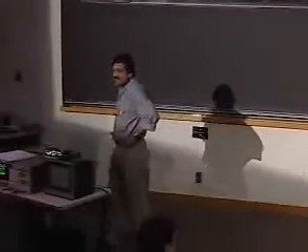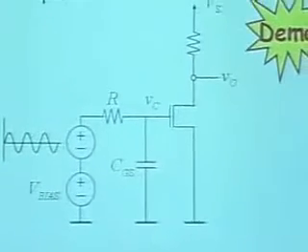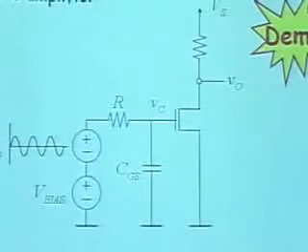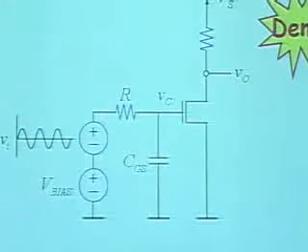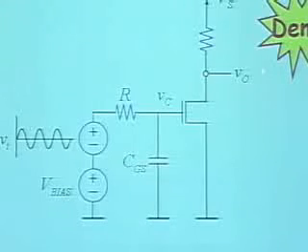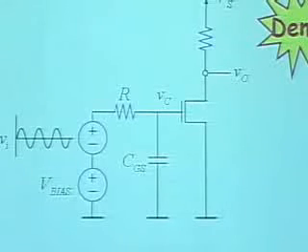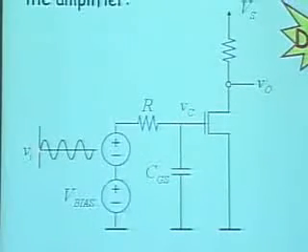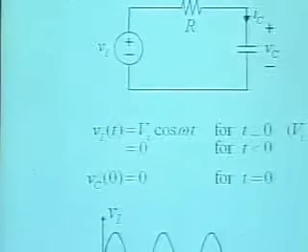That is weird. And today we will look at why that is so and try to understand the frequency behavior of this little subcomponent here. Notice that VC is exactly 180 out of phase with VO. So VO is faithfully an inverted, amplified form of the input VC. However, VC itself should have been the same as VI, but it looks quite different. So let's understand why that is so.